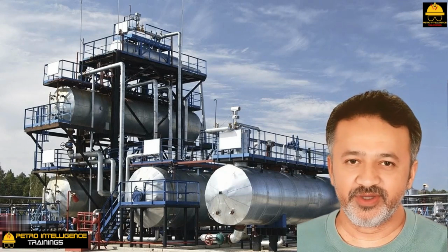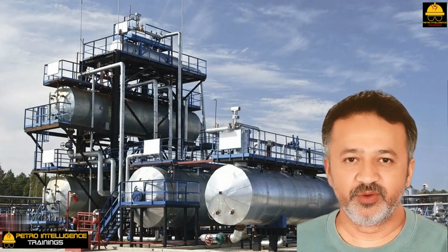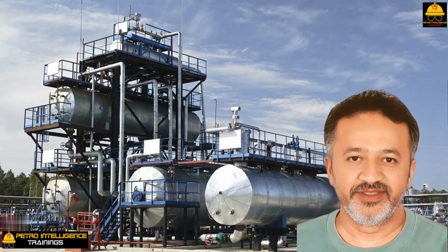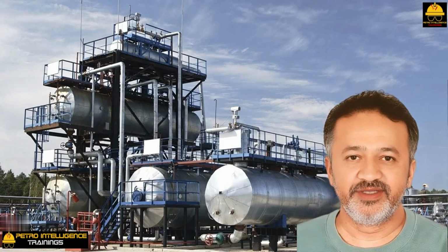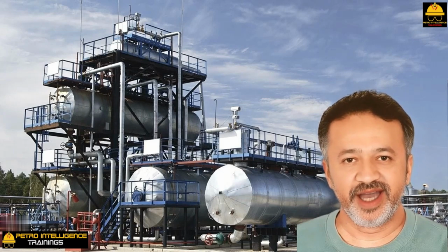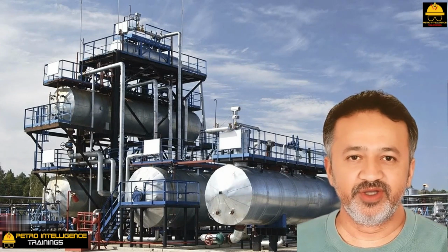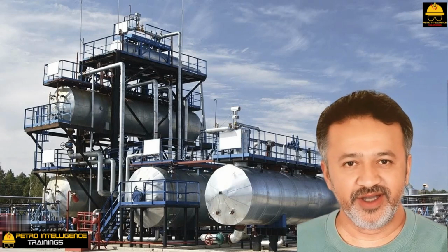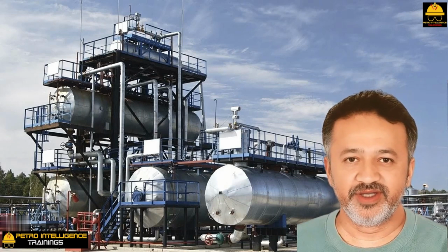Oxygen is a particularly reactive element. Actually, oxygen is a very potent gas and reacts aggressively with exposed metal surfaces to form oxides. Of all the corrosive substances encountered in a process plant, few exceed oxygen in reactivity with steel pipes. If a considerable amount of oxygen is left in boiler feedwater, interior corrosion of the boiler tubes will be rapid. The bulk of the oxygen, or dissolved air, is stripped out of the boiler feedwater in a deaerator.